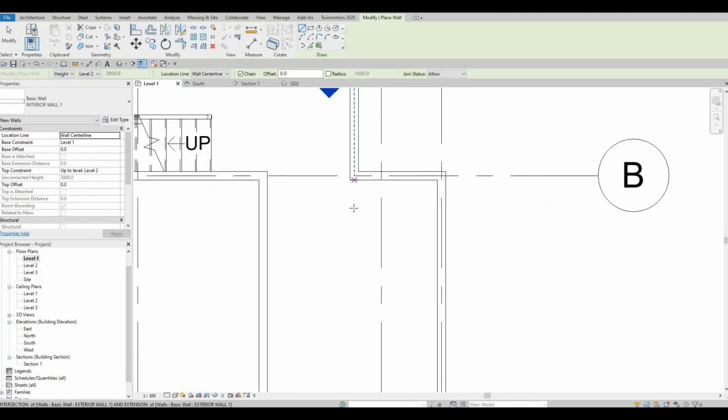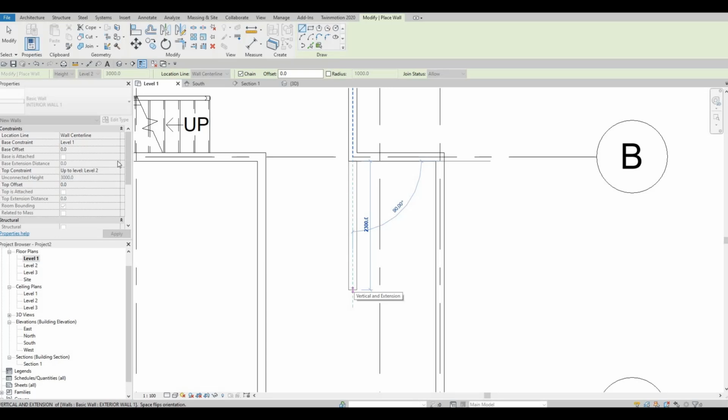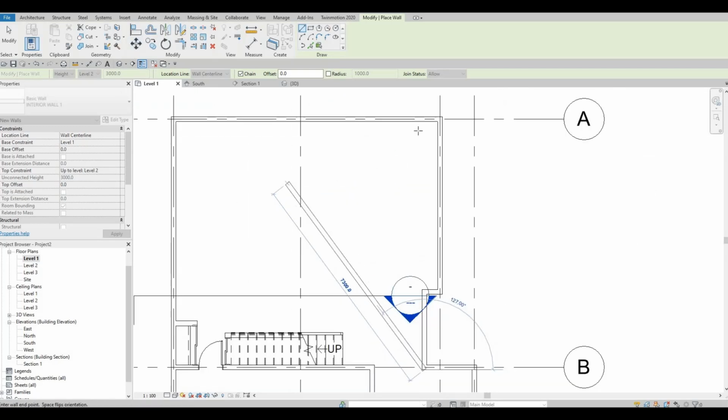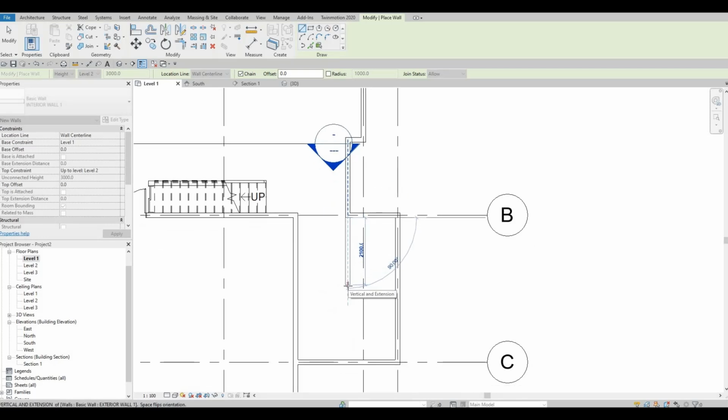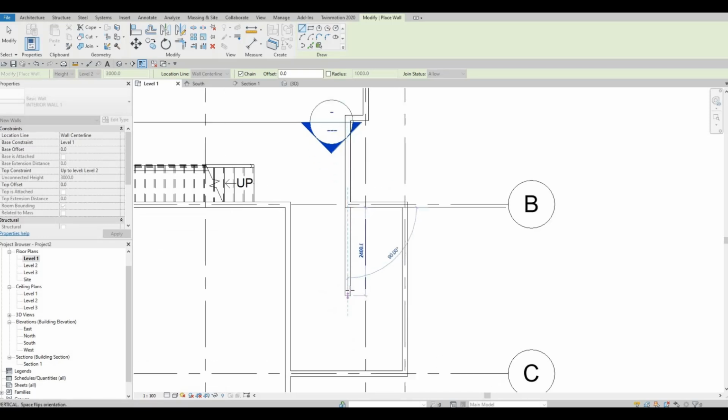So that's something that you should know, so that you don't need to keep on looking. Because once you loaded a lot of stuff, it will be hard to just keep on looking for it and then adding it. So once you have it right there, you can always use copy command or create similar if you're doing it like a wall right here. So now we're going to add it like this.